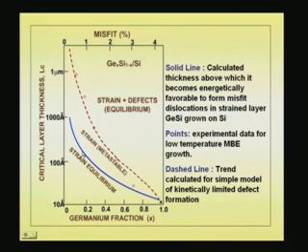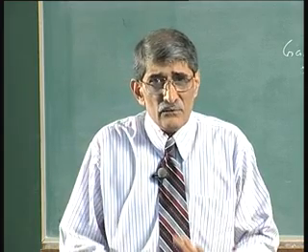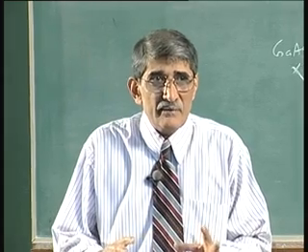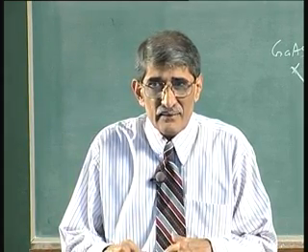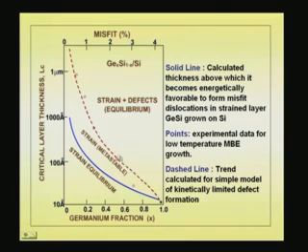This was the initial theoretical value. But if you do this growth by ultra high vacuum techniques like MBE, you can get thicker layers which are defect free. In the sense, as you grow, you do not provide the high temperature required for them to break up the bond. So, it grows without breaking the bond for thicker layers. That is what is shown here, the dotted line. The dotted line is the one which is called metastable, in the sense you grow it at lower temperature, though at this point it has a tendency to create defective layers. If you grow at lower temperatures, you can get thicker layers, not too thick. You are not pitching for very thick layers. Base width, you are talking about 0.1 microns. So, you are happy with that. If you are able to get 1000 angstroms, that is quite sufficient.